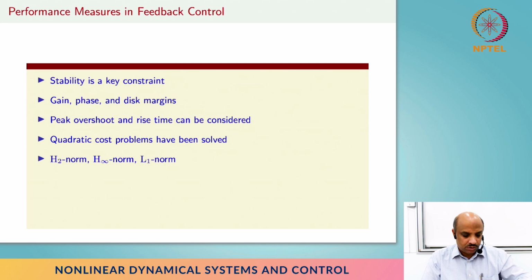L1 norm is actually another very interesting norm, again the same kind of induced norm where the input is assumed to be bounded, output is assumed to be bounded in infinity norm sense, the maximum value, and L1 is the induced norm. And for a long time it has been an open problem, and then eventually they solved for certain special cases, and there's been a lot of work. The L1 norm is probably the most practical norm that one should work with. So these are all different performance measures.